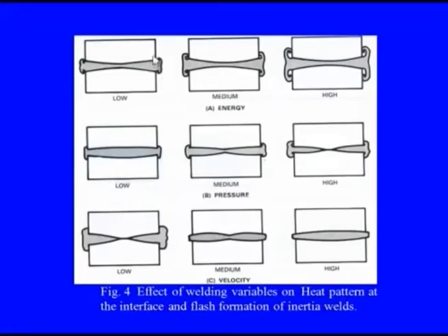The higher the size of the flashes, the choice of the corresponding processes to remove these flashes will be different, as we have already seen. For minimal flashes, probably we can go for some polishing kind of processes, but if the flashes are bigger like this, then we have to go for some serious machining processes.